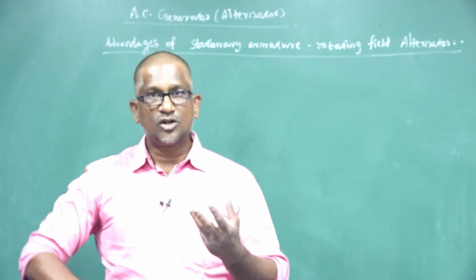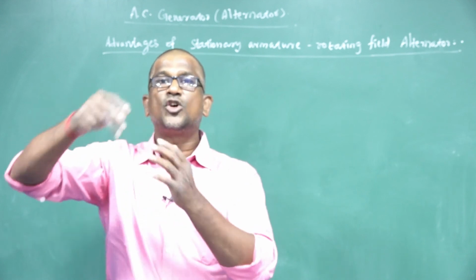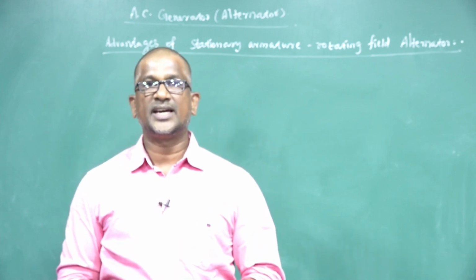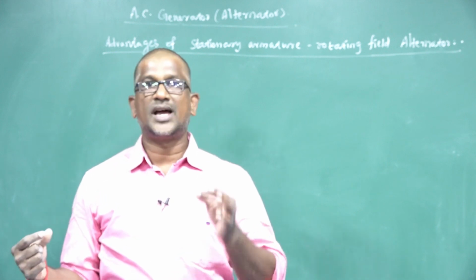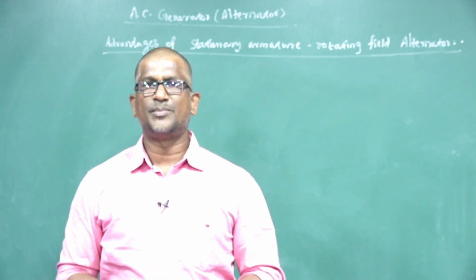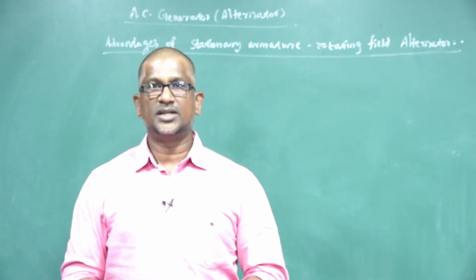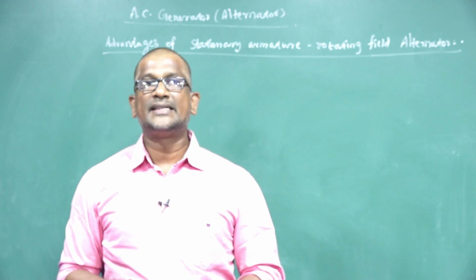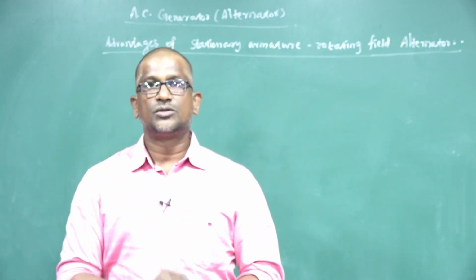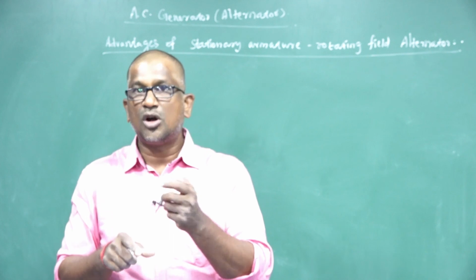Next, the rotor. The rotor is the rotating part of the generator. It consists of magnetic field windings, and these windings are placed on the salient pole. The salient pole is magnetized by using a DC source. The physical contact between the DC source and the magnetic field windings is made by two brushes called carbon brushes. The ends of the magnetic field windings are connected to two sliding contacts called slip rings, and the slip rings are attached to the shaft. So whenever the shaft rotates, the slip rings and the magnetic field also rotate. So this entire part is called the rotor.